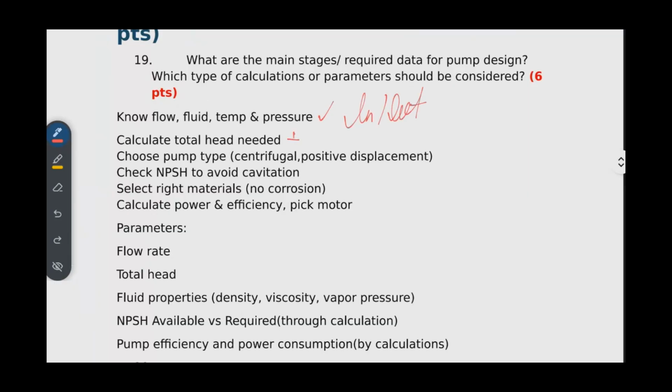Calculate total head needed. Choose pump type. Yes. After having all the required data, you can easily look at the charts to understand what type of pump you will use. Is it centrifugal? Is it PD type of pump? In general, from most of the manufacturers, you can easily find on the internet what type of pump could be used for these applications.